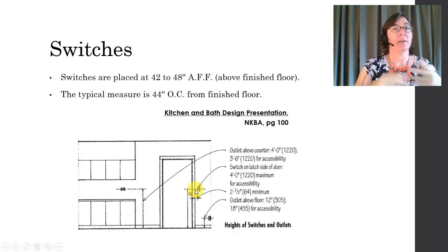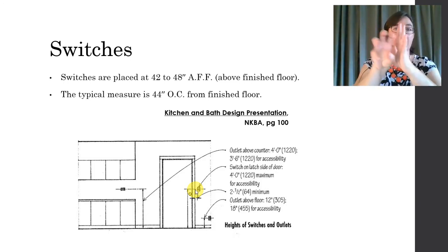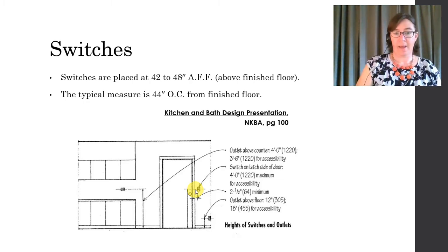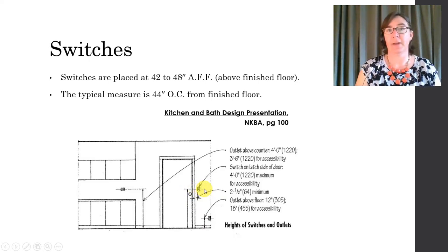And that's generally determined by the studs inside the wall that are forming the jamb of your door, and then they attach the junction box to those studs. All right. And then the height, you can specify this, and it's generally 44, maybe 48 inches.